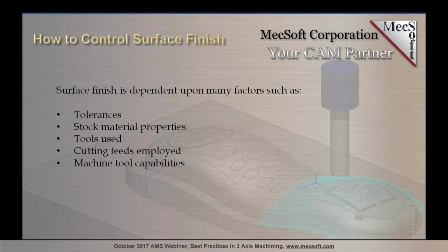And again, in the blog, we have some best practices that you can look at, but a couple of the best practices I'd like to mention here before I turn it over to Uday is, you normally want to use machining regions that contain your toolpaths to flow with the geometry of the part. And then you can also use different cut patterns and directions of cut to obtain better surface finishes, and Uday will talk about that as well. So this part of the demo is going to be focused on surface finish and how you can control your surface finish.